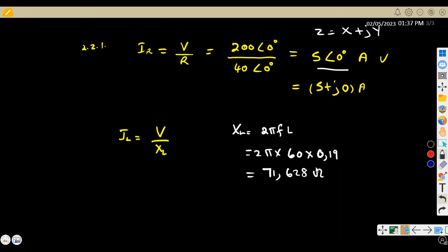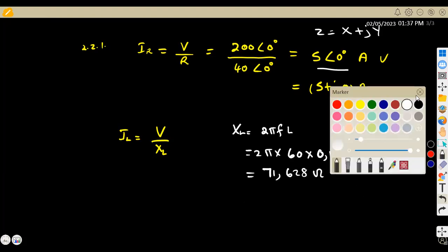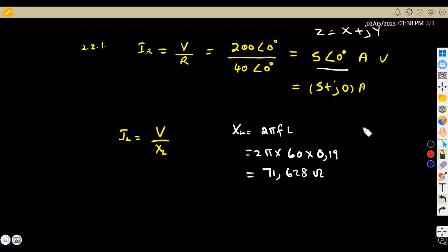Okay, but remember that inductance leads. So it is supposed to be in this format. Remember, let me write it this way. We're supposed to have the resistance. If it is the impedance, we are supposed to have the resistance plus jXL, or actually this is ZL. But we do not have this resistance, so in place of the resistance, you write it as 0.